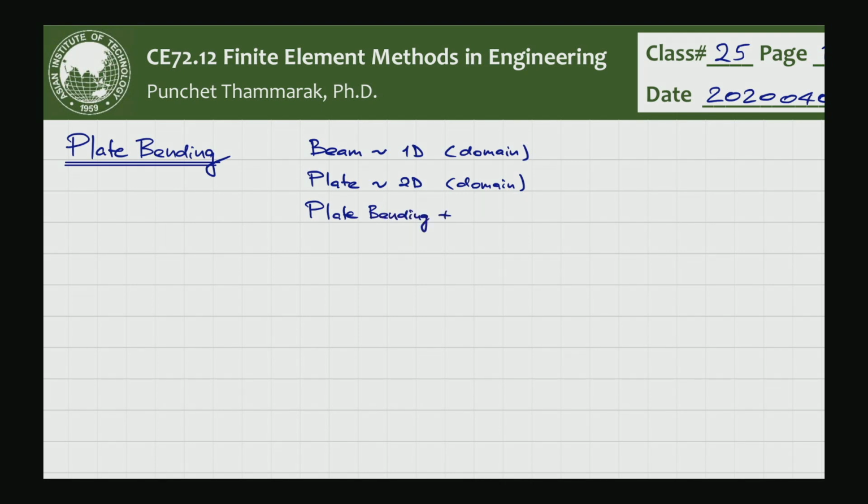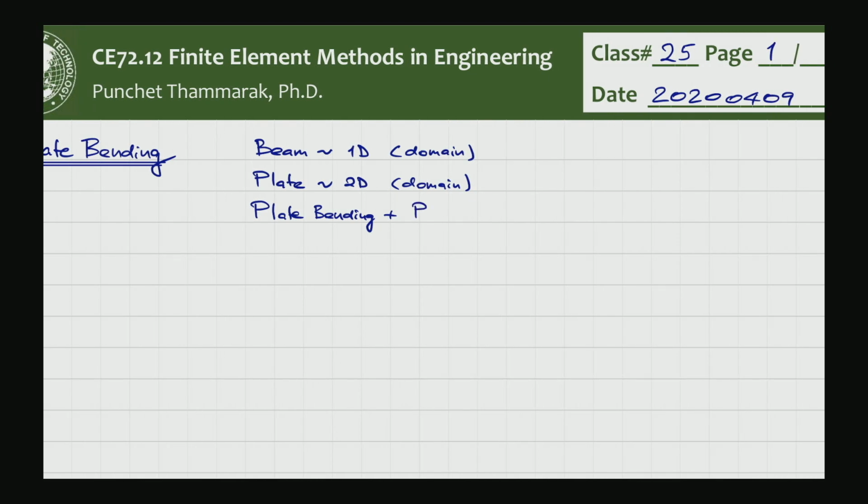So if you combine the plate bending to the plane problem, which is a plane stress, sometimes people call this one membrane. Anyway, you will be getting the shell element that incorporates all bending and in-plane behavior.